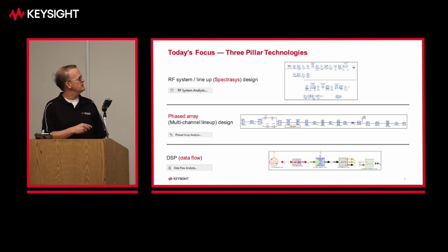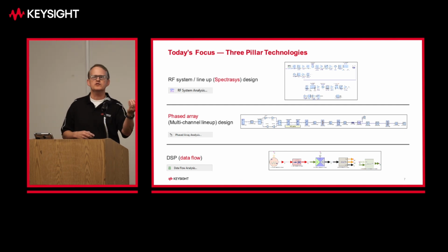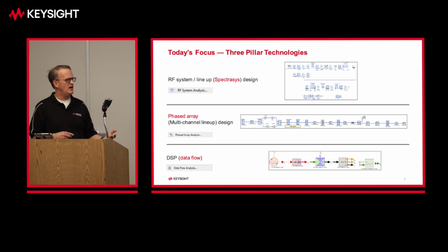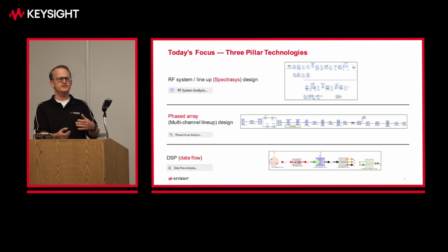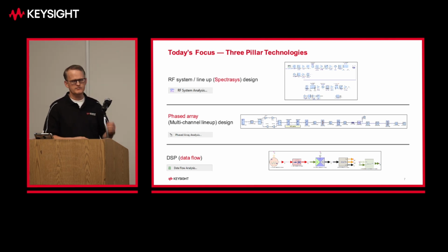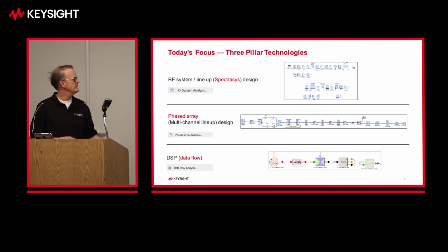So at any node, it'll tell you how much gain, noise figure, compression, noise behavior, all throughout the system, and the spectrum at each node. So, that'll help you with things like spurious analysis, troubleshooting, and even things like spectral emissions mask. I had a customer that was going to the FCC with a raft of spreadsheets to prove how their phase array system behaved, and stayed within a spectral emissions mask. This tool will help you do that with what ifs, and keep you within, and even generate a nice clean report, not a raft of spreadsheets.